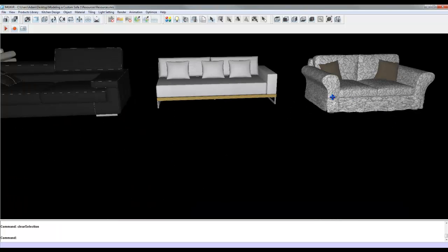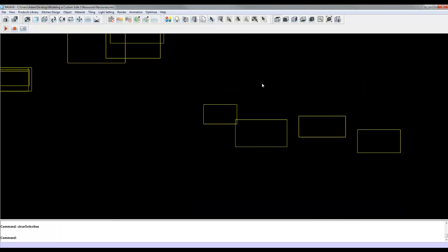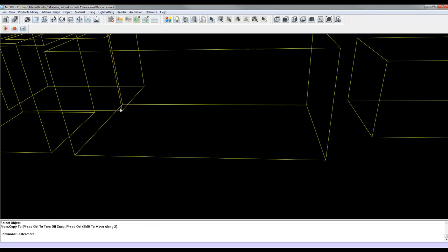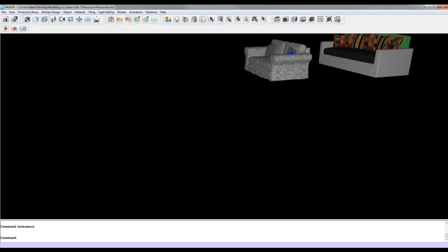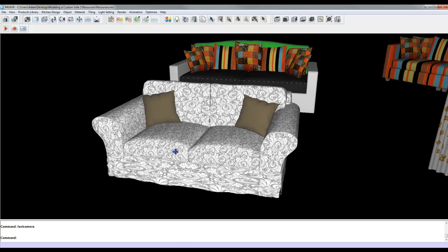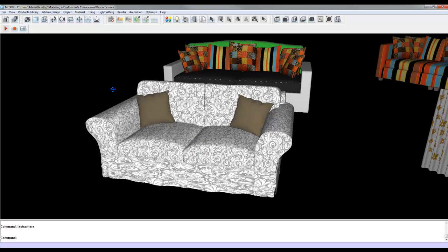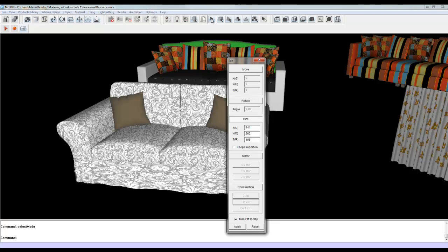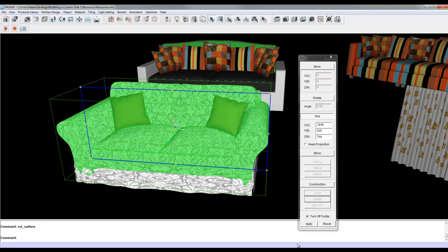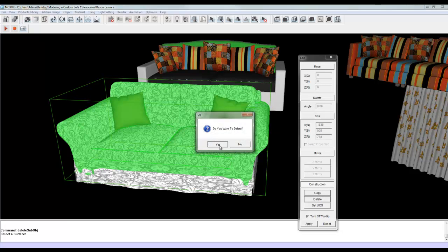The last bit is just the little cover piece. So, using this model here, I'm just going to copy it across. Just go object copy, move that across to where it needs to be, over there. Go back to last view. Okay, and once again just delete everything except for that slipcover part. So once again we can go to our selection arrow, surface, holding down shift because I've got my box selection on. You can select everything here. Construction delete, there we go.